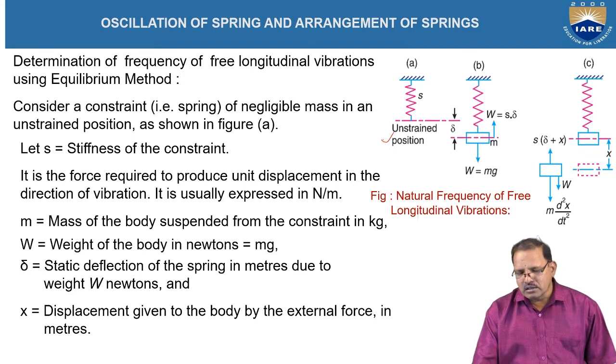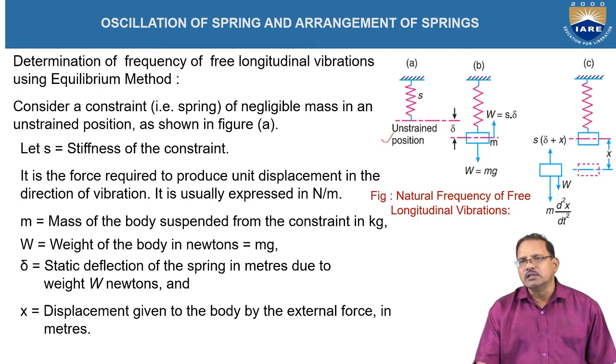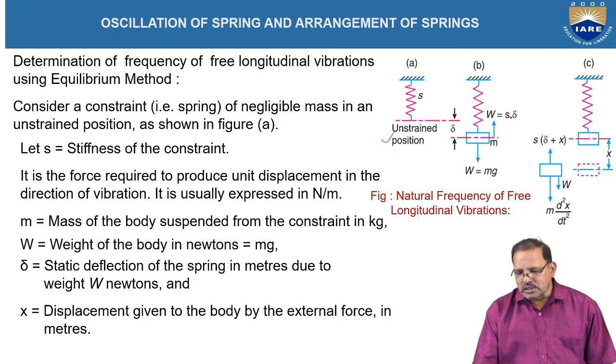Hence, while moving towards the equilibrium position, this elastic energy is converted into kinetic energy, and hence it moves upward from its equilibrium position. This process is repeated. That means the body moves up and down with respect to its vertical axis. These vibrations or motions are called longitudinal vibrations. Here X is the displacement given to the body by the external force.